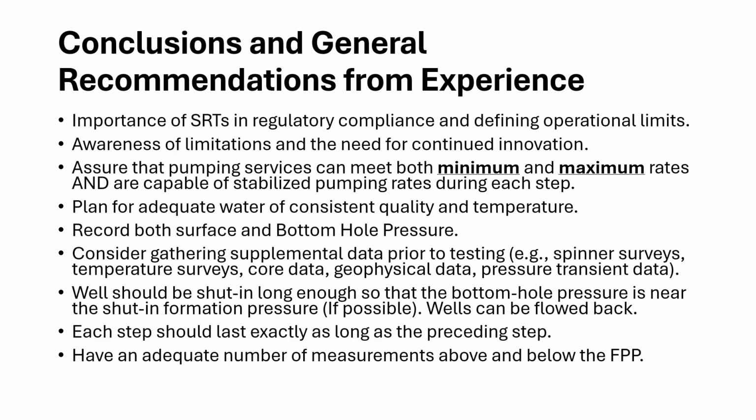And then going on, we should shut in the well long enough so the bottom hole pressure is near the shut-in formation pressure, if that's possible. If that's not, wells can be flowed back. So each step should last exactly as long as the preceding step. That's crucial. And have an adequate number of measurements above and below the formation parting pressure.